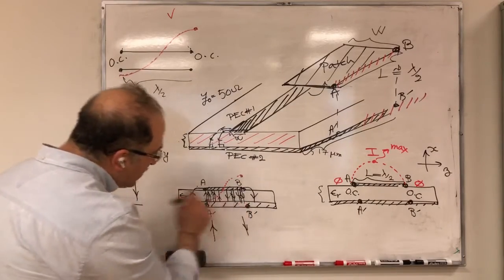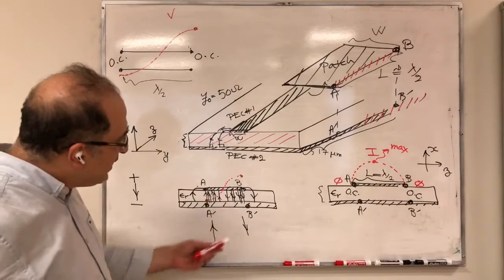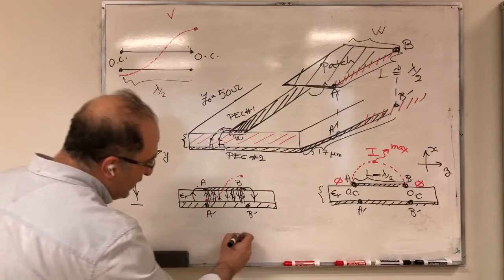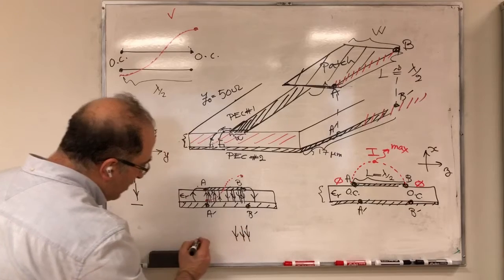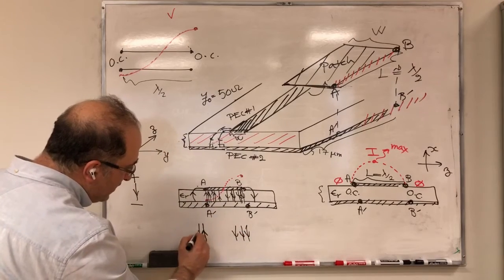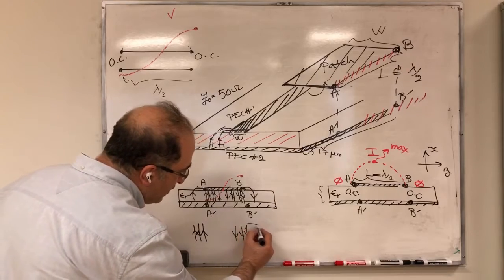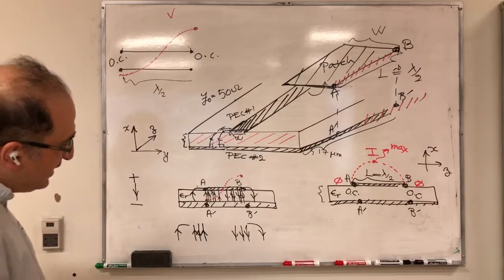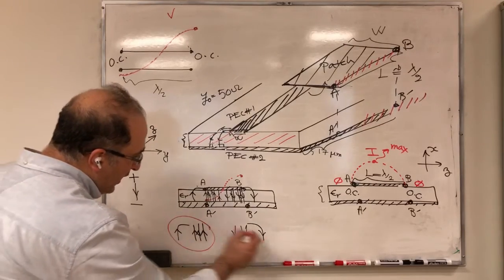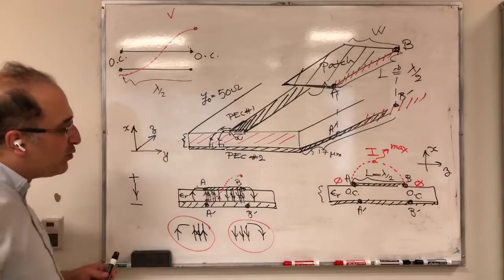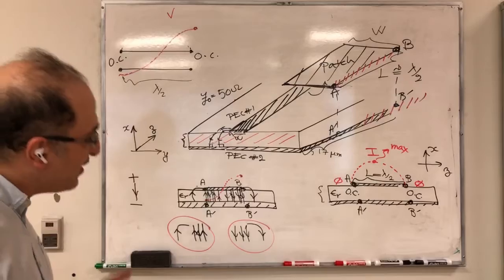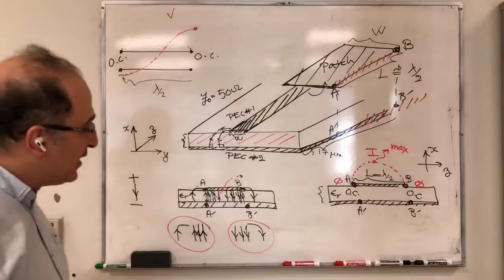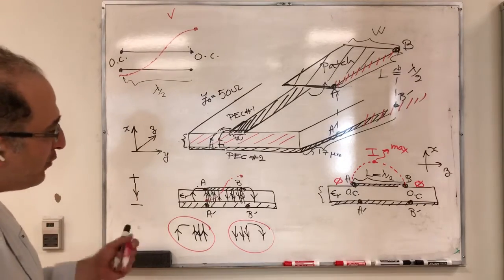And if you look at the direction of this electric field, you actually see a cancellation effect again, because I can just plot them here. Here, these are very strong. Here I have these, and then you have your fringing effect in the same direction, similar to this. So now if you look at this part and this part, you see that your electric field is also going to be opposite to each other. And that makes sense because remember, this is half a wavelength. If you go half a wavelength away, everything is going to reverse. So far this is our observation.